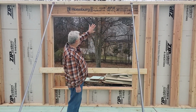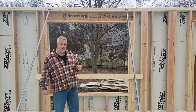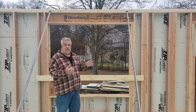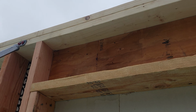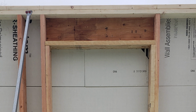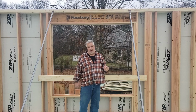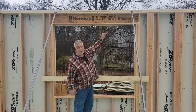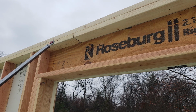But here we have what I term the pocket header. And a pocket header is nothing more than taking the components that are required to carry that load and push them out to the sheathing, revealing a slight pocket on the inside. Now, to complete that pocket, we have a 2x6, just like our sill, at the bottom of the header, and I call that the head plate. What the head plate does is it just finishes out that rough opening to the same dimension of the rest of the opening, meaning that 5.5 inches.